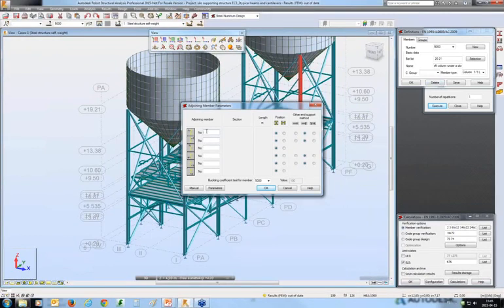As always, for any option that you try for the first time, try to make a sample model and type the numbers of the joining bars being the number of the superbars. For example, a chain of beams or elements that stands for a beam, and compare the value of the buckling coefficient for the element that you want to check with the results you have got for automatic buckling calculations.